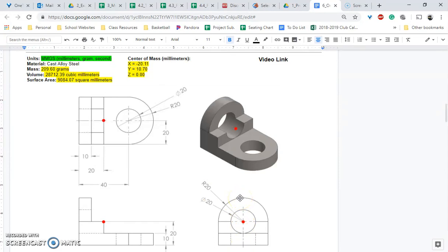Now you could do this multiple different ways. You could draw rectangles and then draw the negative space up here and that arc and extrude cut. You could also do this in an additive fashion where you're actually drawing these arcs and adding onto it. But the confusing part there is if you try to draw from the right side view and you have this image or this sketch, when you go to extrude back, you actually added material right here that's not here. So then you would have to go ahead and draw a sketch to delete it.